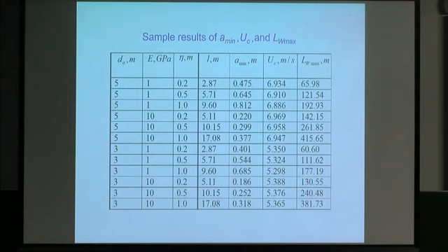Given the water depth, the E value and the thickness of the cover, and typically in the river, this is about the range of the ice cover thickness you will have. And here is another one, with depth 3, you get something like this. And you can see the value is in the range of what they observed.